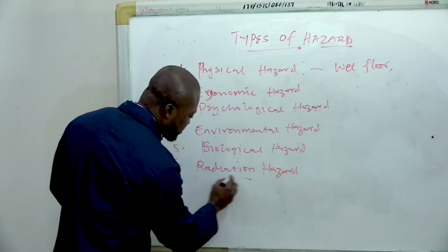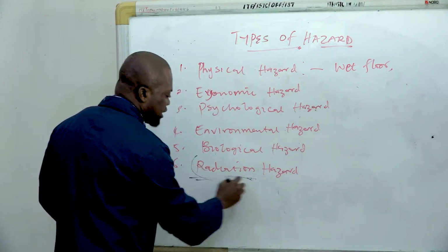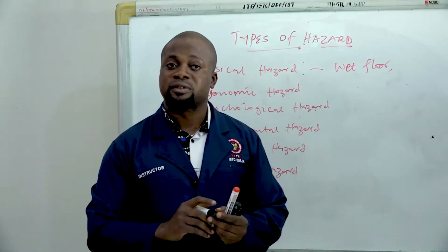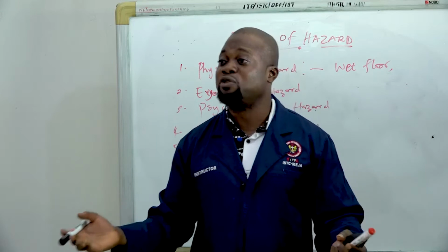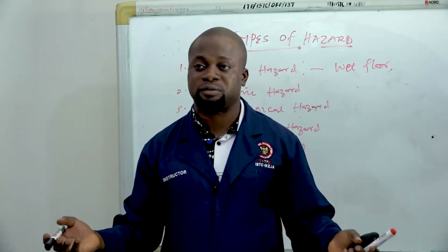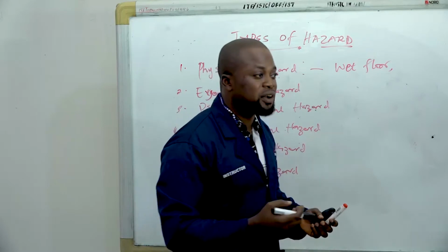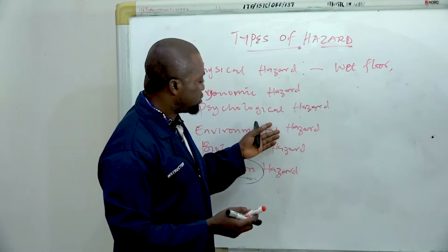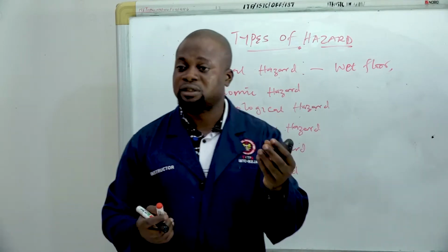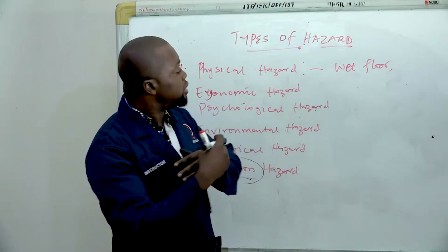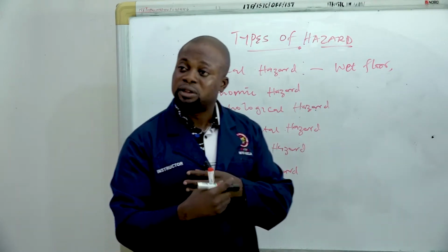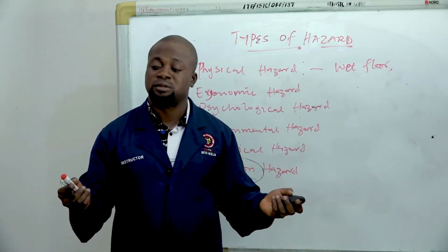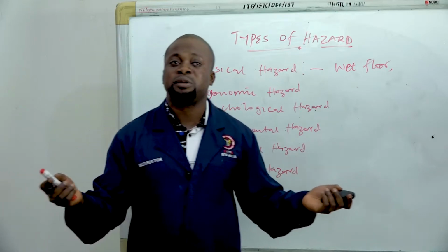Then we looked at radiation hazard as it concerns us. Basically, this is very, very important to electrical personnel. Because sometimes we say there are some accidents, we say out of God, it just happened. Like a situation of arc flash in electrical materials. Once it flashes, it can cause laceration, burning of the skin, and once it is done, there's no turning back.